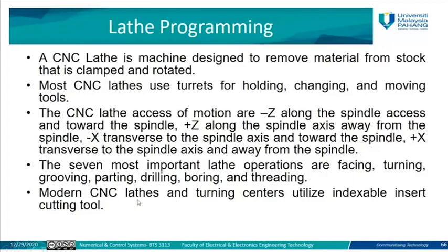So a modern CNC lathe, or turning center, utilizes indexable insert cutting tools. Even if you try with the simulator, you can see different types of tools. Some tools come with the cutter on the left, some with the cutter on the right, some with the cutter on the top, and so on. There are also different sizes of cutters and different purposes for these tools.